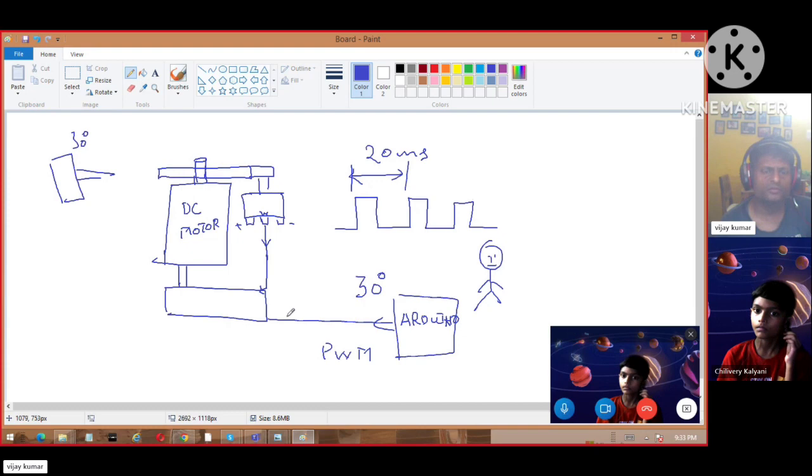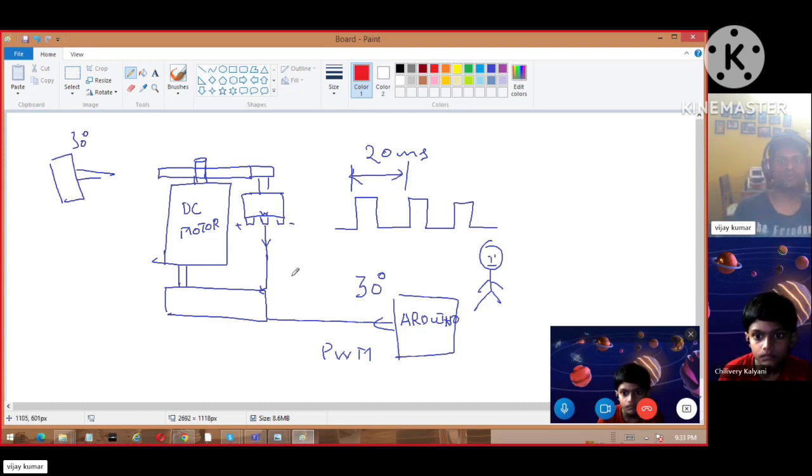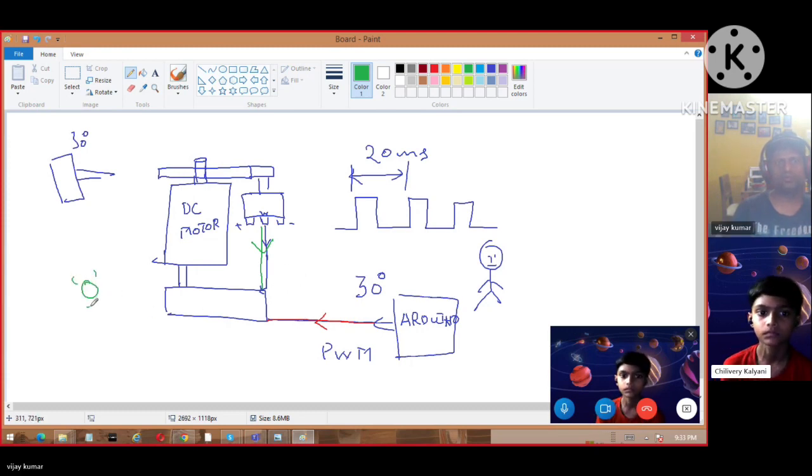So once the signal goes to the servo motor controller, of course there will be a comparator which will compare both these signals. For example, let me differentiate this one with a red color, and this one with a green color. You understand, if the difference between these two signals is 0, then the servo motor shaft will stop rotating. Imagine if there is some error.